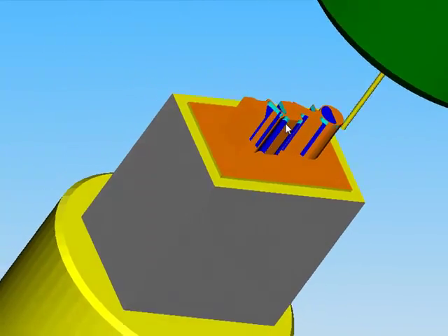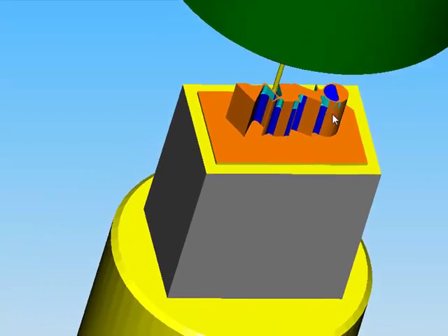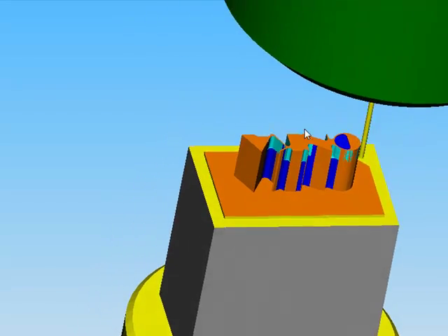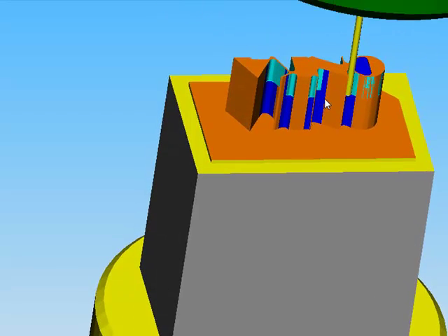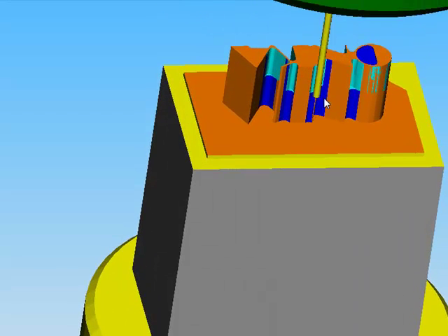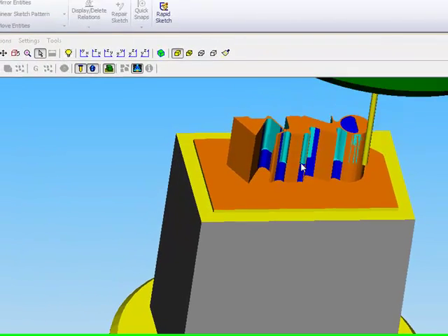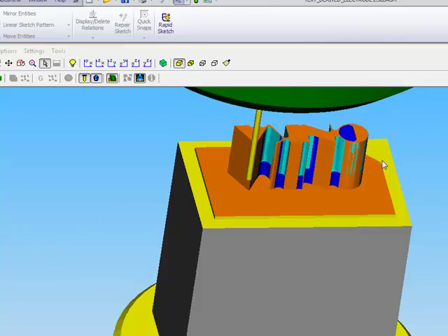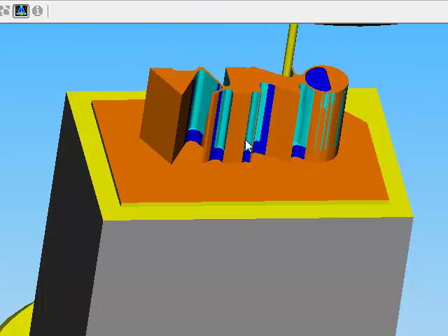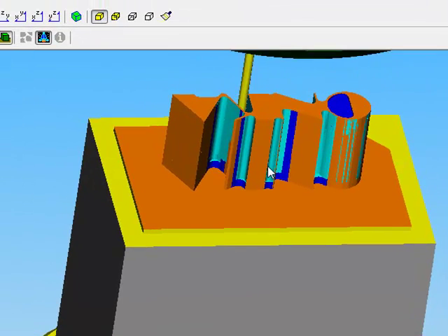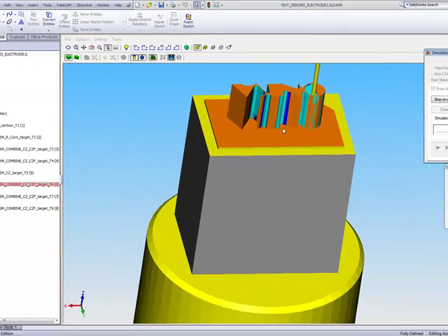As you can see now, we've gone to the next step to get even further down, and slowly but surely, the text is now starting to appear on the part as it's being machined down. We're still not at our smallest tool. We still have two more operations that we still have to do. But every single time we do this, we get closer and closer, without breaking our end mills, to that final destination of using that 0.1 millimeter end mill as we go around.